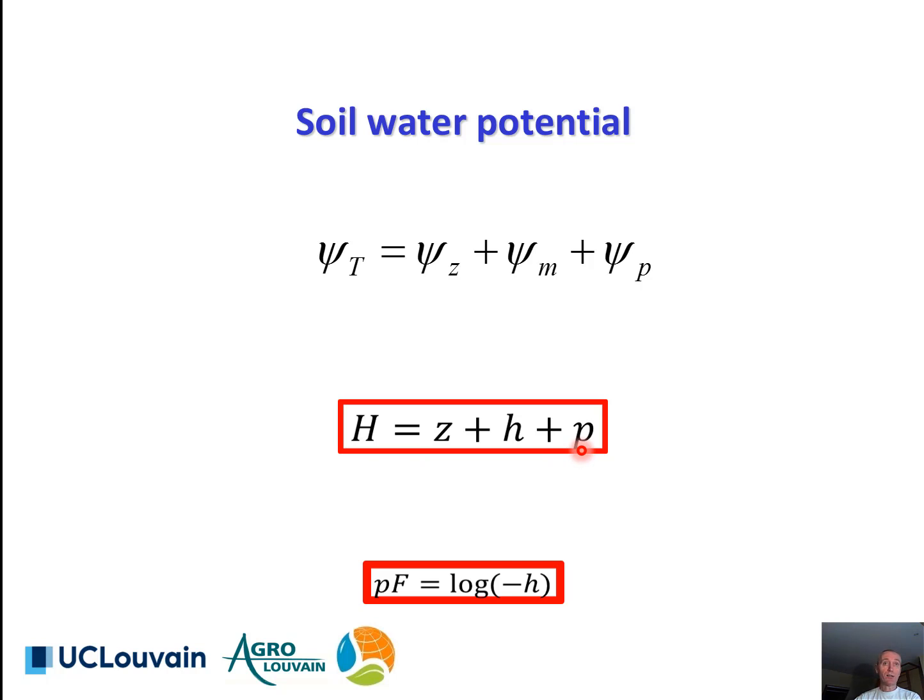In case the soil is not saturated with water, the capillary head or suction head, H, will develop. The magnitude of H will depend on the desaturation state of the soil. Indeed, if the soil is very dry, soil water will mainly be situated in small pores. In these small soil pores, the capillary forces will be very high.